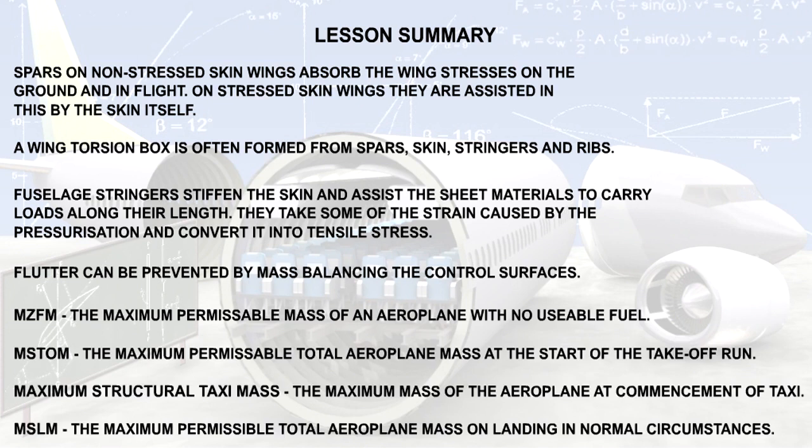Finally, you should know the meaning of the various maximum structural masses to which an aeroplane is limited. Remember that the maximum zero fuel mass of an aircraft limits the bending moment at the wing root, while allowing the maximum load to be carried.